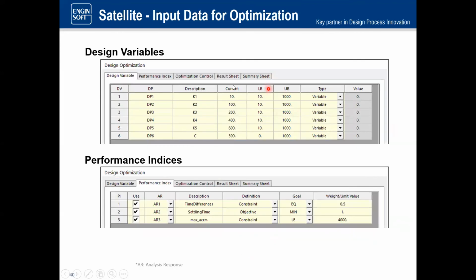So then in mapping that into Recurdyn, we can see this is the AutoDesign panels. So we just simply apply all these design variables with the lower and upper bounds, current values. We can see these are the 5 different stiffnesses for all the joints between the panels. And then performance indices.